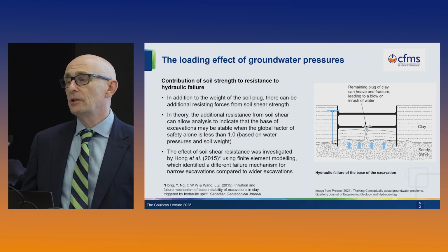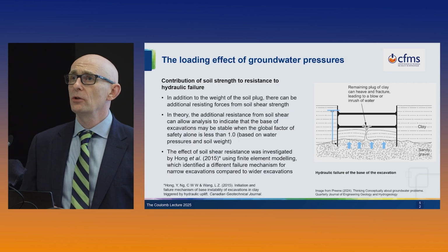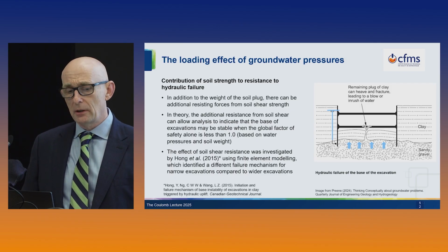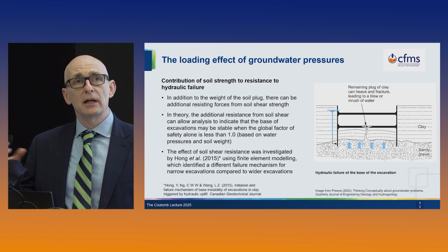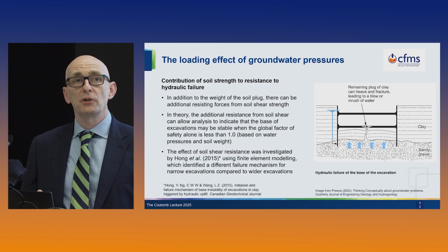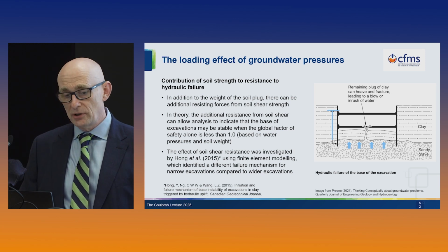But when we do analysis, sometimes we think, well, the clay plug has some strength. What can we do? How should we apply the strength of the clay plug in these calculations? Because in theory, you can apply some of the soil shear strength to that clay plug to show that something will be stable even when the groundwater pressures are high.